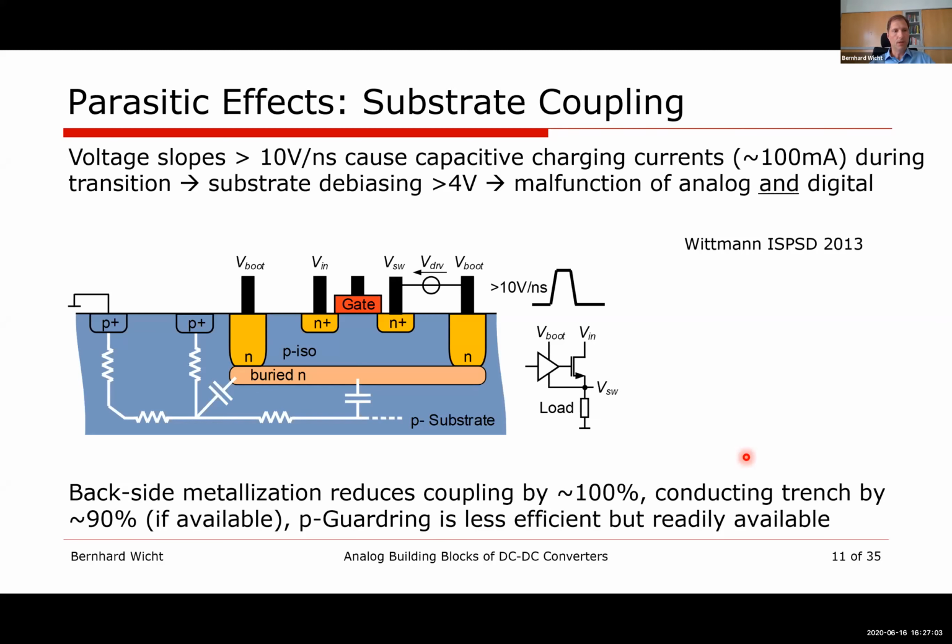And especially if you do a high voltage design, and I assume if you talk about SOI, SOI is of course really great for high voltages, up to a couple of 100 volts. And then of course these slopes will be simply steeper, and so we get some coupling. So SOI is great, except that we need to take care of the coupling effects. Okay, thank you very much.